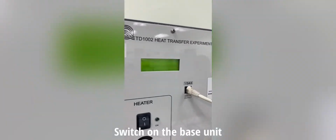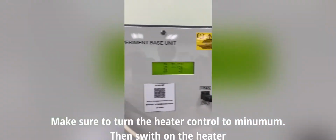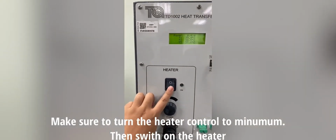After that, the base unit is switched on. Before switching on the heater, we need to turn the heater control to the minimum. After making sure the heater control is in the minimum state, then we turn on the heater.